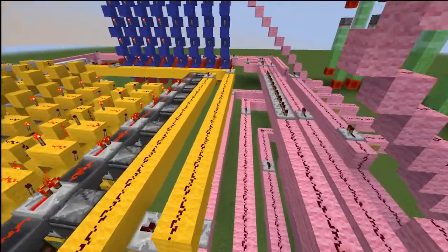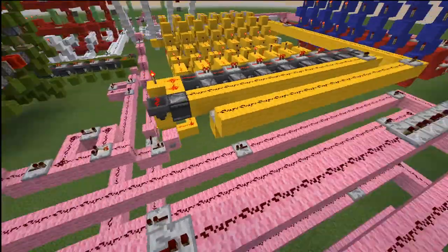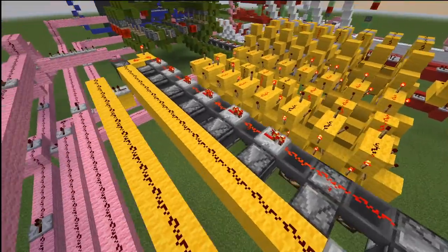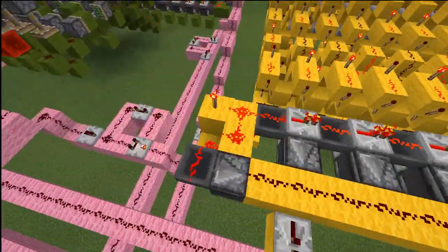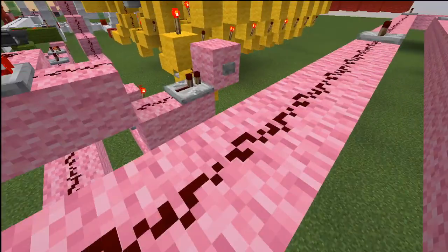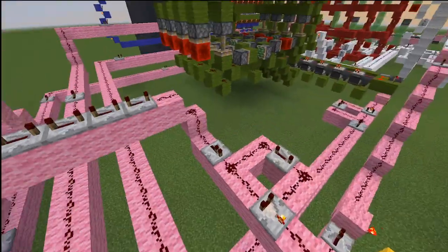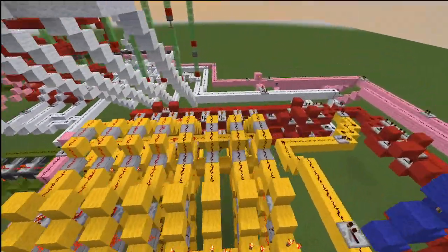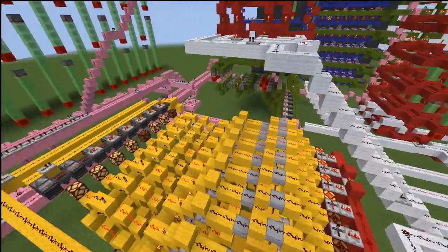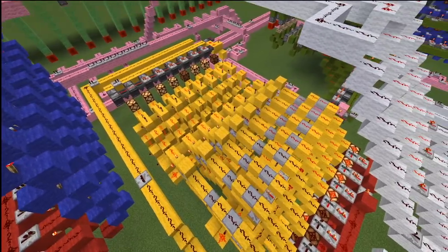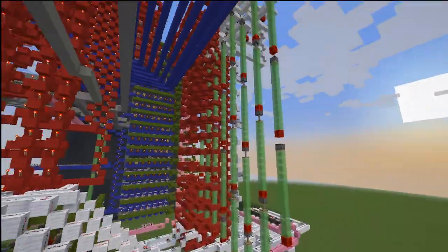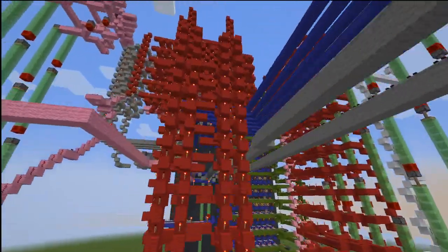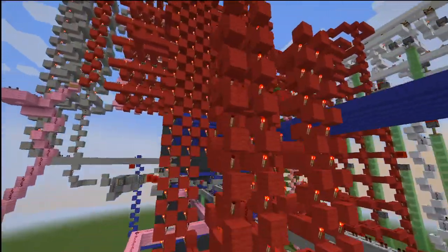And if the control unit sends a signal to do so, it will actually send data from this ALU via right here. It will send data from the ALU to the A register right there, so you can keep performing operations using this ALU. It is a combinational circuit. It's one of the only combinational components in this whole computer. And right here is the instruction register.